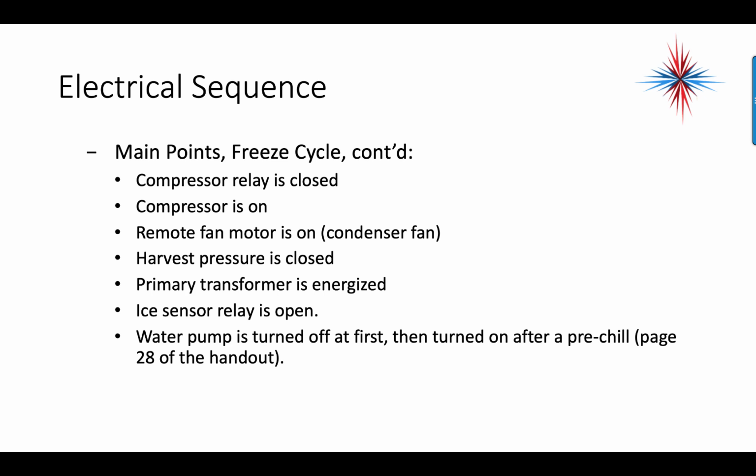And the water pump is turned off at first and then turned on after a pre-chill. In other words, what happens in this machine is the water does not circulate across the evaporator until that evaporator has cooled to a certain temperature.